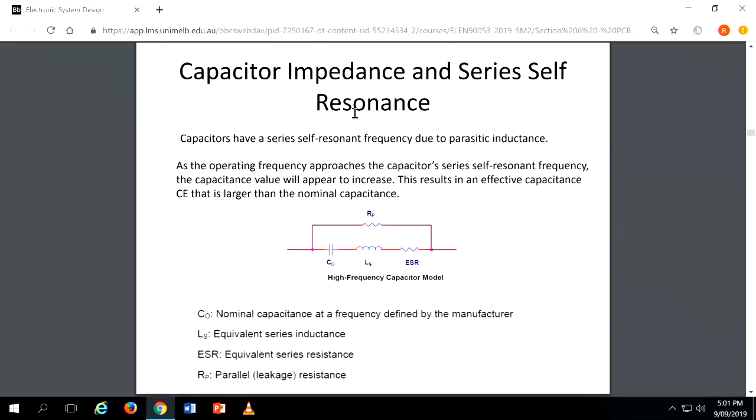We have got the parallel lines, 155 megabits per second. We use a parallel to serial converter and make it 2.54 gigahertz, and then drive the laser diode. Then we got some communication, on-off PPM. Then again in the receiver we are detecting using a photodetector, then amplifier, transimpedance amplifier, then again serial to parallel conversion. So whatever is coming into the board is so many parallel lines, 155 megabits per second, and then we are serializing. So that's the reason 20 megahertz is not really a high frequency.